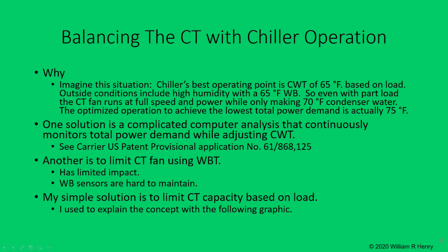The objective when optimizing a chiller plant is to have the lowest overall average energy use over time, but just controlling to the lowest, most efficient condenser water temperature for best chiller efficiency can cause a cooling tower to overuse energy for a significant portion of the time. Up to half of the efficiency gains with the chiller can be lost by poor cooling tower operation.